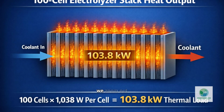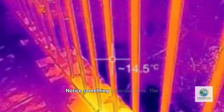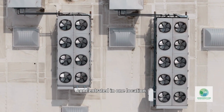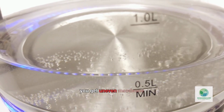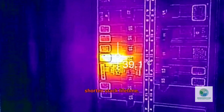In image number 2, we zoom out to a 100 cell stack. Each cell produces approximately 1,038 watts of heat. Multiply that by 100 cells and you get 103.8 kilowatts of thermal load. That is the heat that must be removed just to maintain steady-state operation. Notice something important here. The heat is distributed across the stack. It is not concentrated in one location. That means your cooling system must remove heat uniformly. If one section runs hotter than another, you get uneven membrane degradation. You get localized stress, you shorten stack lifetime.